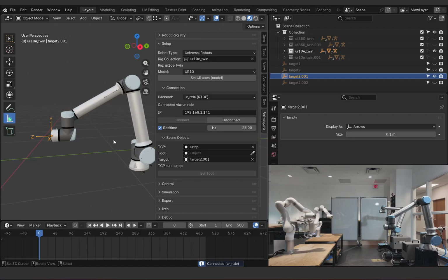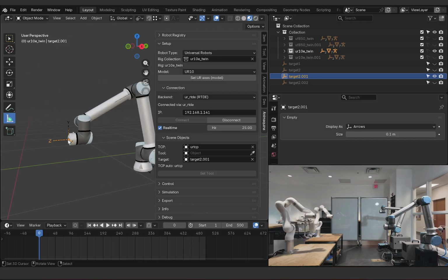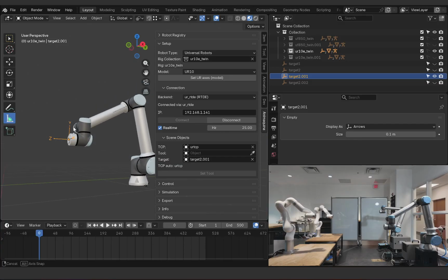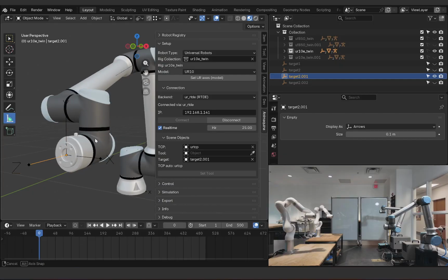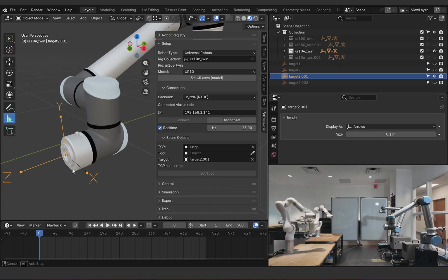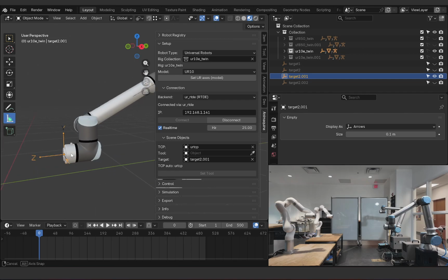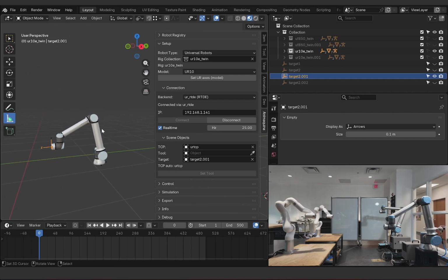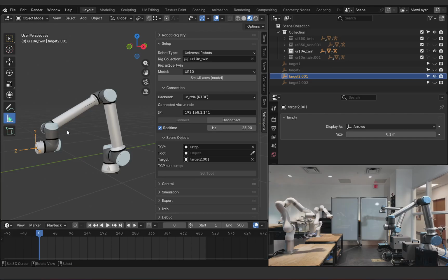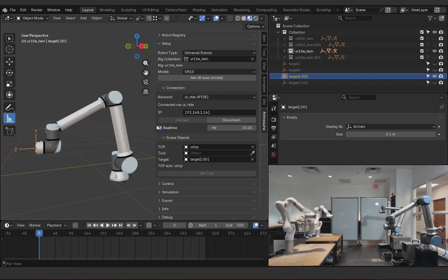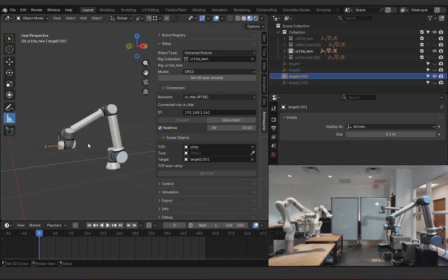Now, Animaquina by default is going to first find the TCP position of the current set tool. So in this case, we can see that there's no toolset, so our TCP position is right in the middle of the flange. And also, Animaquina is reading in real time the position of the different axes of the robot, the different joints of the robot. So if you go and jog the robot now, actually on the actual pendant, you should be able to see the robot updating